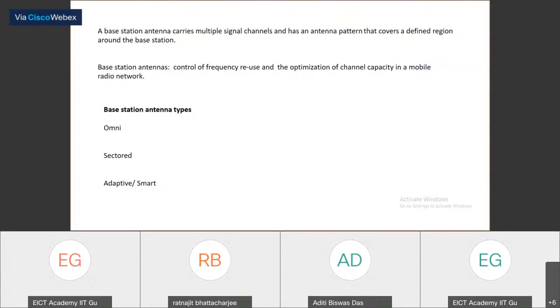And in the center of the hexagon, you will place an omnidirectional antenna. But later, people found that there is benefit in splitting this hexagon into sectors. So, for example, if you take a hexagon and put 120-degree sectors, then you split the hexagon into three parts. So this sectored antenna became very popular after the second generation of the cellular deployment.